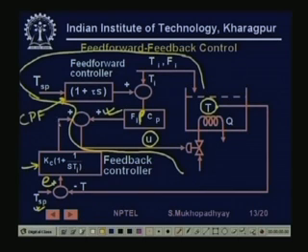So this is my U feedback and this is my U feed forward, which together give U. Suppose there is a modeling error in rho, so rho is maybe slightly less. Then the control input due to only feed forward will now be a little less.